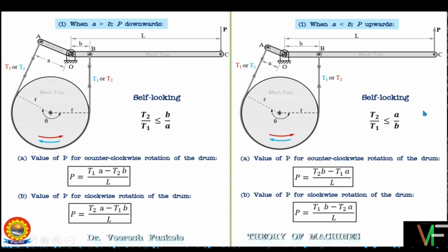Having seen the condition of self-locking, we should understand where the self-locking is required. The advantage of self-locking is taken in hoists and conveyors where the motion is permissible only in one direction. If the motion gets reversed somehow, the self-locking is engaged, which can be released only by reversing the applied force.